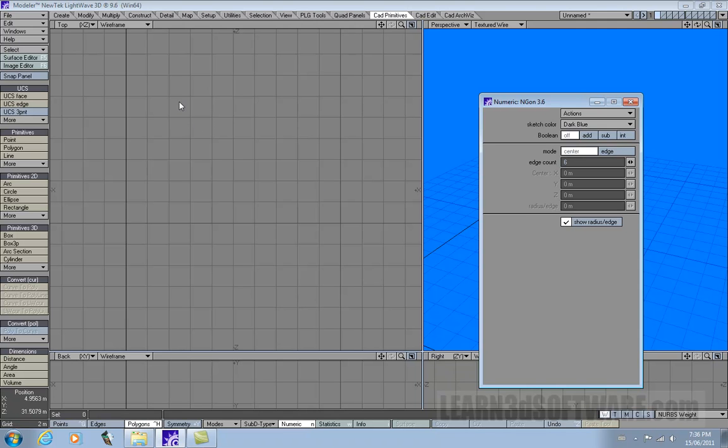Let's left click on the canvas and just drag out. Very similar to the circle tool in radius mode. The crosshairs allow you to move it out, and the round widget at the end, if you drag it out straight along the same direction as this blue line, you can make it bigger or smaller.